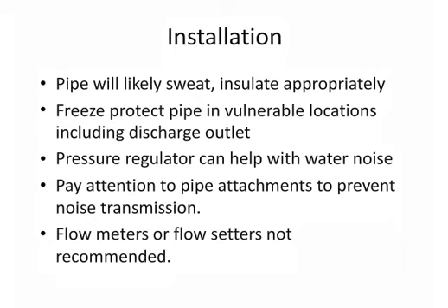Pressure regulators sometimes can help with water noise. You've got to be careful that you're not introducing the rushing sound of water through a pipe that gets transmitted through the home. And again, that includes attachment of that piping to the structure, so you're not transmitting and amplifying. I really encourage you, flow meters and or flow setters are not recommended. They typically will cloud up. You won't be able to see them as far as the flow meters, so it's just a temporary fix. You really don't want your homeowners having access to that kind of information anyway. So again, just keep it simple.